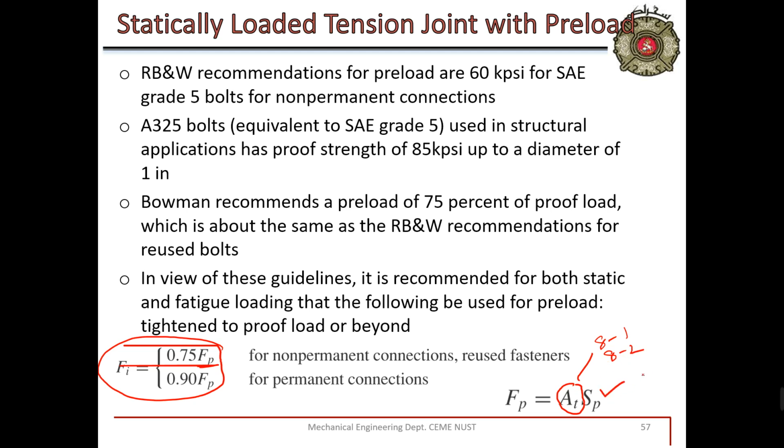This Sp you can use from Table A-9 to 11. From this Sp, you can calculate the maximum load that this bolt made of this material and of this diameter area can carry. This load, you can apply how much external load that can be applied for a preload.